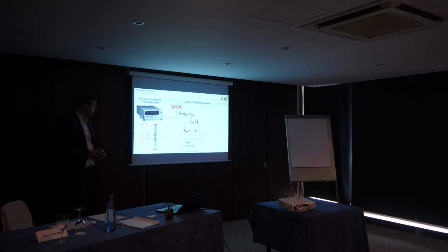and the specific part of the resistance contains, since Matthiessen's rule says that, a thermoelectrical effects part and the non-temperature dependent part, which is defined by the microstructure, for example pores and microcracks, which is the part I'm really interested in. So I want to measure this part, and to do so I need to eliminate the other part, and I do this with the delta mode.